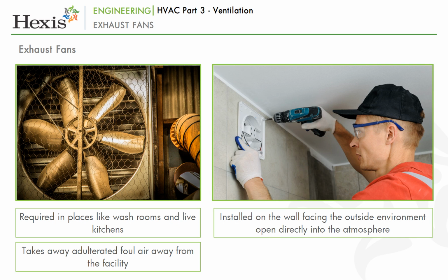The washrooms or any other room having exhaust fans should also have a grill built into the entry door, because otherwise it would put additional load on the fan to throw air out and also create a negative pressure inside the room, which will lead to a high draft when the door is opened. The size or rating of the exhaust fan will depend on the size of the room and the traffic in the room.